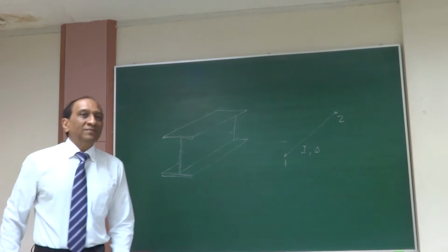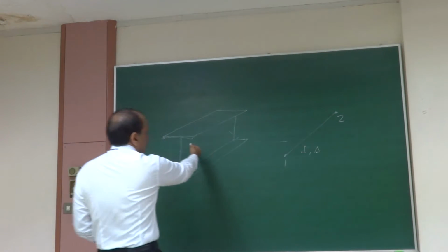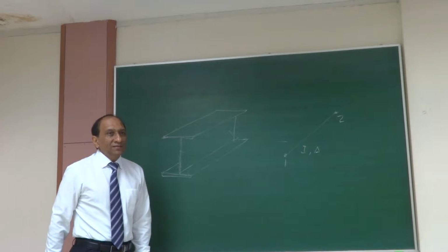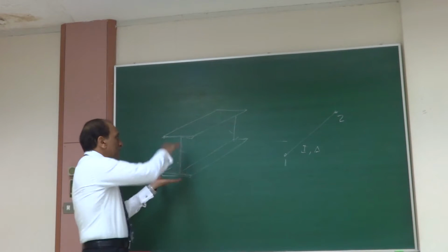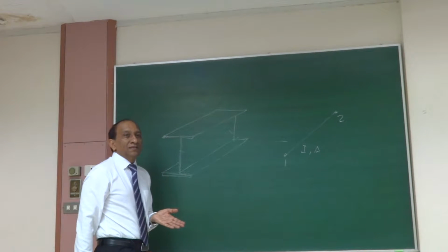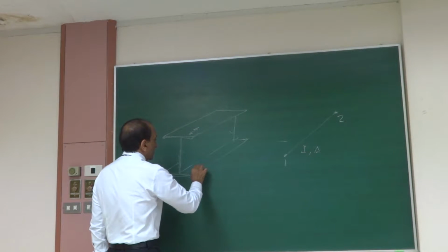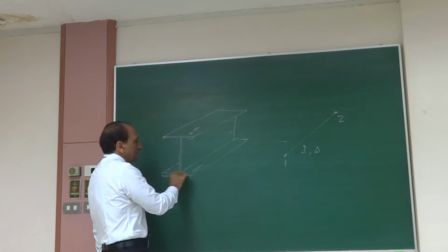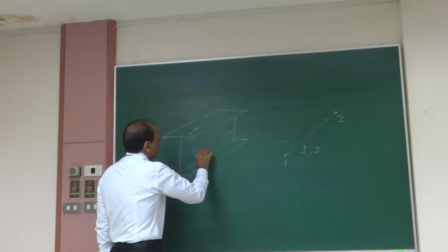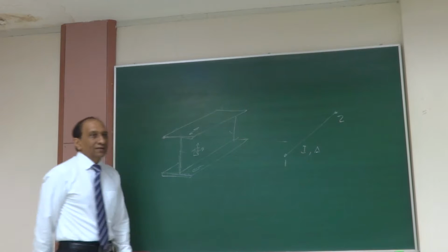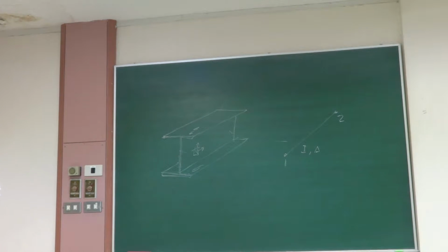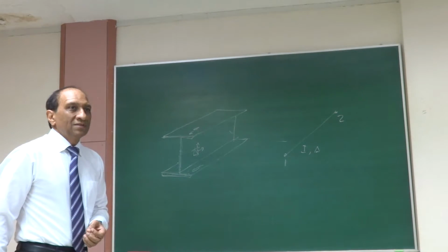Because each one of them is locally, although this has a bending capacity, right? It's a bending element and a shear element, but in reality each one of them is carrying only axial stresses or in-plane stresses. You remember last course I told you, tension, compression. So this is carrying compression, this is carrying only tension, this bottom flange. This has no bending, this has no bending, and this is carrying in-plane shear, which is also composed of principal directions, here and here. So an I-beam, which has a lot of bending capacity and a shear capacity, it's a bending element. Actually, it can be modeled as a set of membranes,